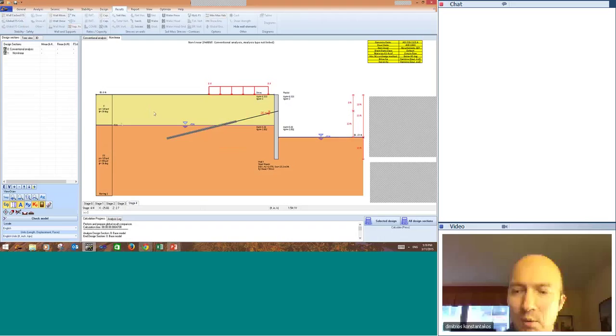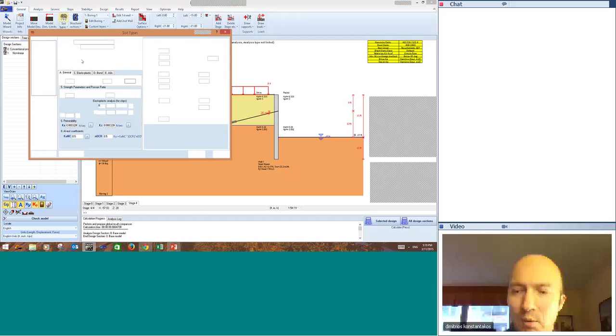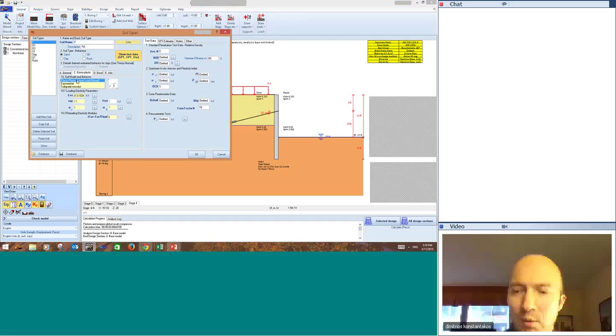But we have to make sure that we edit the nonlinear properties of the soils. So go to General, Elastoplastic. Here's where we have the elastoplastic soil models. We have a linear elastic perfectly plastic, an exponential, and a subgrade reaction modulus. I usually prefer the exponential. So the idea is that we will need some SPT value to estimate the loading modulus of elasticity. We have the exponents for loose sand, coefficients for vertical and horizontal stress, and the reloading modulus for the excavation side. So let's say we want to estimate from SPT.